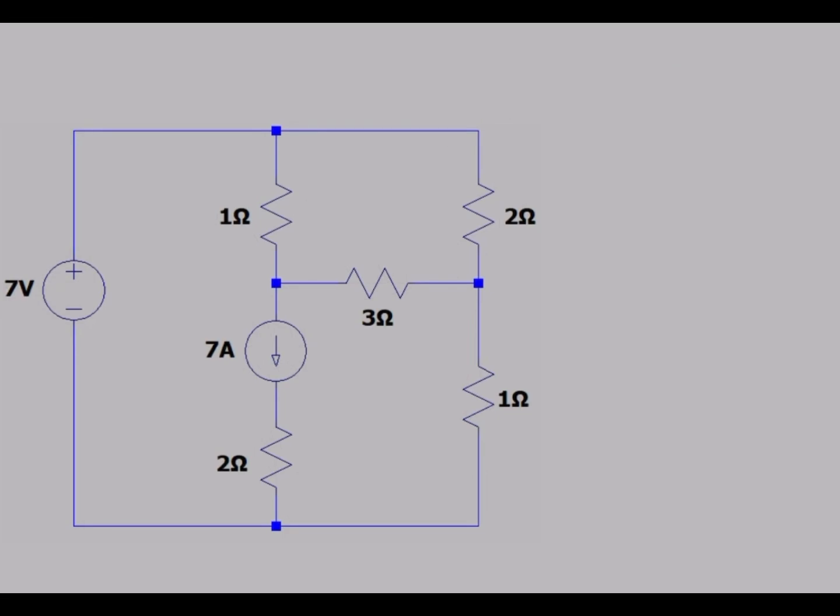For the second circuit, we're going to approach this using mesh current analysis. Traditionally, in mesh analysis, you would look at your circuit and identify each mesh that is present, which are the smallest enclosed loops, and assign them each a current variable that we will subsequently use to write KVL equations for and solve. So we can start with the bigger loop here and assign that a current variable I1, say. For the top right loop, we could say this is I2, and we could say this is I3. Again, this is arbitrary. It does not matter which variables you use, as long as you stay consistent.